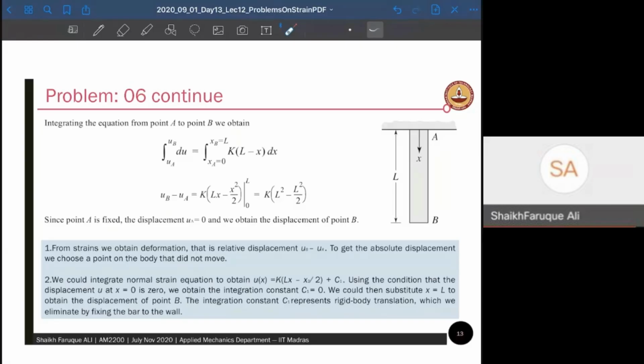Therefore you cannot directly find it unless I give you a simple 1D problem like this. Direct integration is not going to give you the strain components. You need to satisfy something called strain compatibility conditions. That should be added along with your unknown equations, and that will solve the problem. Otherwise, you have more strains, fewer deformations.